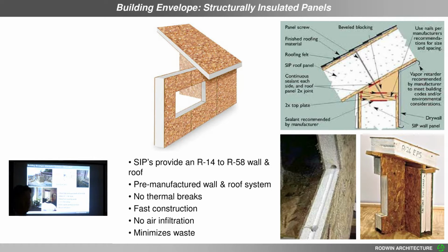And that's a non-toxic binder? No, it tends to be a toxic binder. Almost all of the engineered wood products and the foam products off-gas volatile organic compounds of different sorts. Some of them largely cure by the time you move into them, but some of them, like particle board and cabinetry, and you guys probably know this, can off-gas for decades. So certain types of products can have a strong negative impact on your personal immune system, particularly your respiratory system.